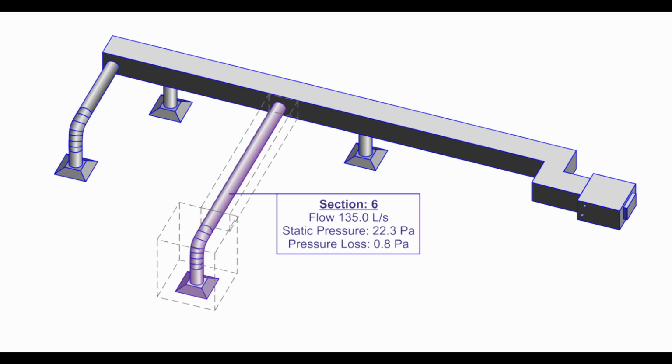Throughout the lecture, we'll unpack terminology, system behaviors, and best practice workflows to help you create clean, analyzable, and coordinated systems. We'll look at how ductwork, pipework, electrical elements, and public health components all join together inside Revit to form intelligent systems. A key objective is understanding why systems matter, not just for connectivity, but also for load calculations, flow analysis, and system reporting. We'll also introduce the system browser, which is one of the most important diagnostic tools you'll